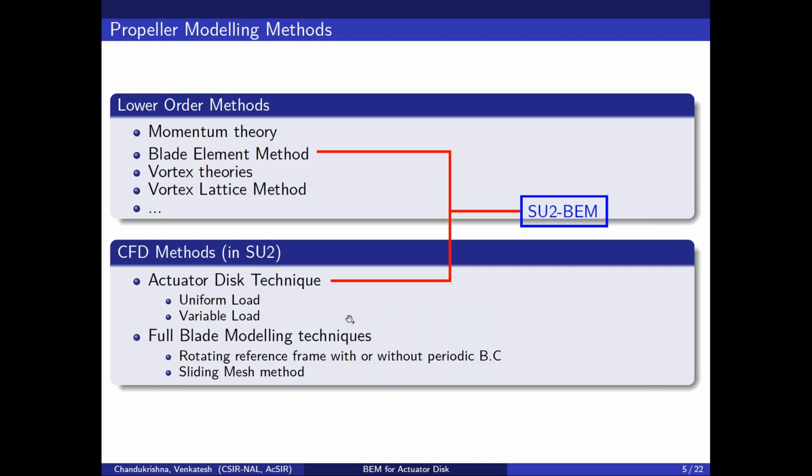And the main focus in this work is to combine two different methods, the blade element method and the actuator disc technique, where the propeller load is calculated using the blade element method. And this technique is named SU2 BEM.